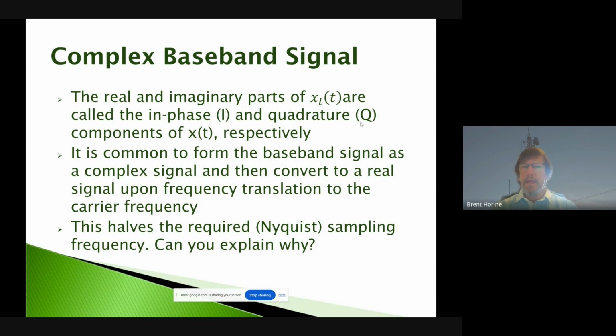So that assumes that we're operating on these with separate circuits, right? And separate calculations. So we're not really getting anything for free. We're now sampling at half the frequency, but we have to do it in two places instead of just one, right? We're having to do it on the I portion of the circuit, that branch, and on the Q, or the quadrature portion of it. So we have to do it twice.